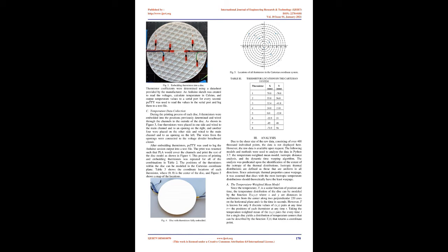The model was sliced multiple times using Ultimaker Cura to transform it to G-code for the printer. All print settings were kept as the default values as shown in Table 1, except for infill density and infill pattern. An AG Create Gmax 1.5 XT printer with heated bed addition and PLA filament from Hatchbox was used for all prints. A post-processing script to pause after the channels had been printed, at a height of 8.89 mm, was added in Ultimaker Cura. G-code was produced for 6 combinations of process variables as shown in Table 2 and saved to an SD card before being printed.